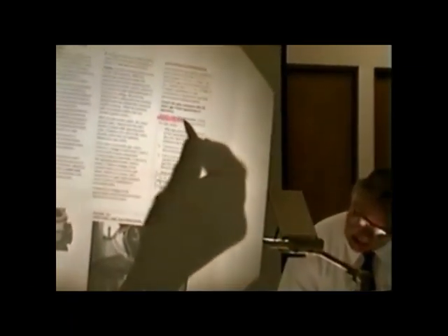Supply gas measurement. Gas pressure should be 5 to 10.5 inches water column. So what we're telling you, gentlemen, is that the minimum is 5 inches water column. If you're working with LP, of course, the minimum is 11 inches. But the page there tells you that we want a minimum for natural gas of 5 inches. Typically, you're going to end up at 5, 6, 7, 8. That's about it. Okay?